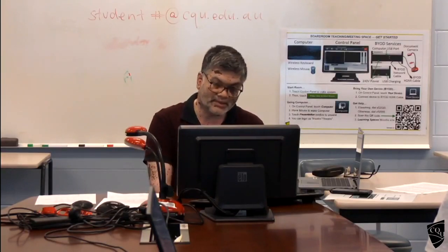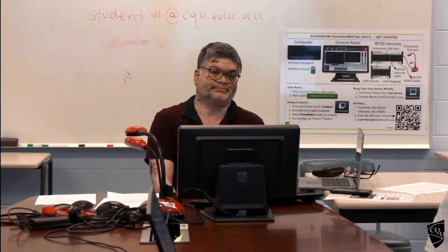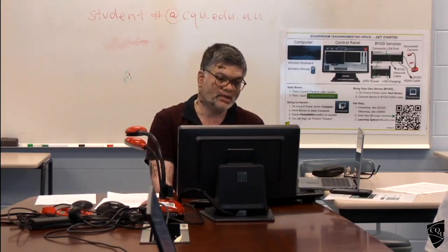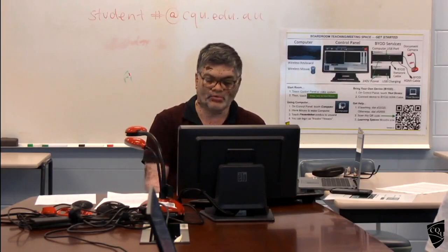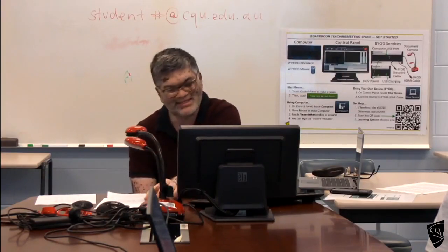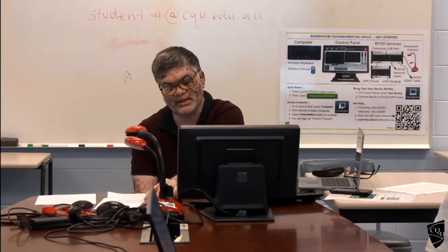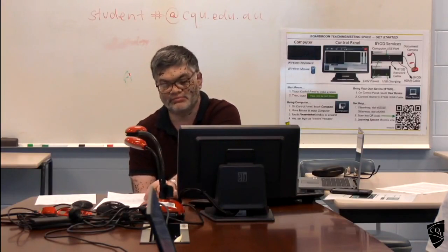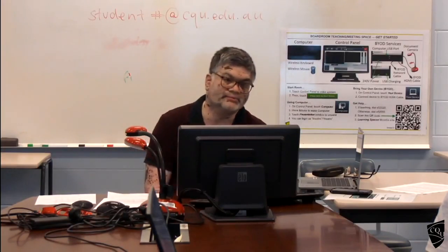So we have the column strip and the middle strip. Obviously, the column strip will take more moment. So if you have, let's say, 100 here, the column strip may take 70 and the middle strip will take 15 here, 15 here, something like that.